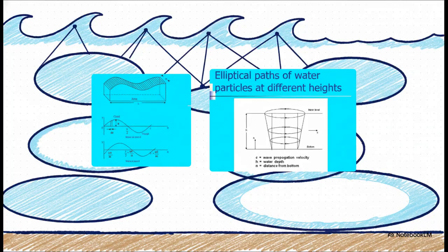Now, if we look past the surface of a wave and peer down into the deep water column, the kinematics are completely different. On the surface, a wave just looks like a simple, two-dimensional, progressive sine wave, right? Just moving from crest to trough. But underneath the surface, those water particles aren't actually just moving forward. They're rotating in place in an elliptical path. Near the surface, that path is almost perfectly circular, but as you go deeper and deeper, the vertical axis shrinks, and those ellipses become flatter and flatter until you finally hit the ocean floor.